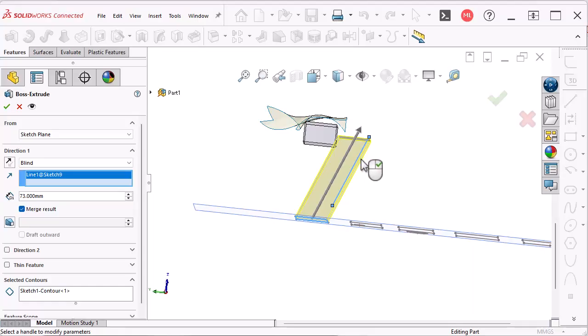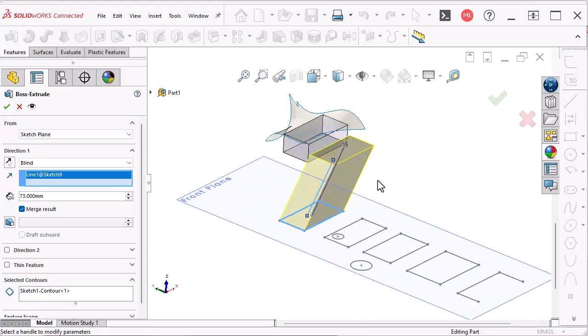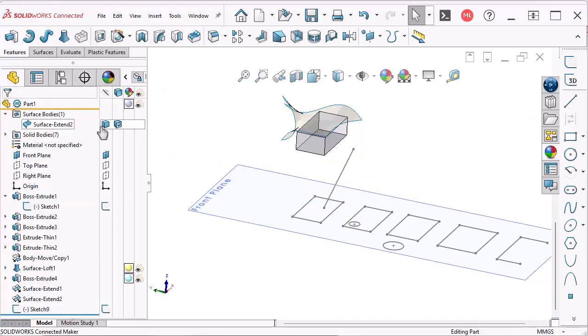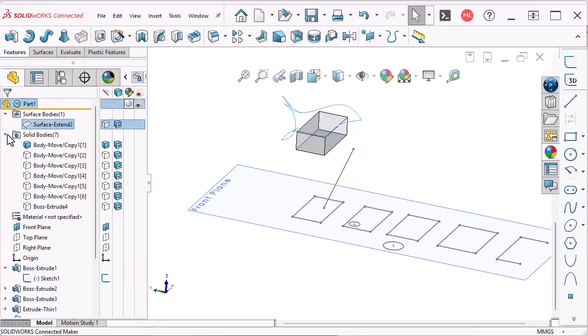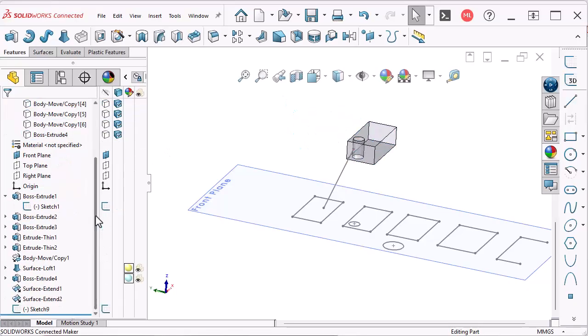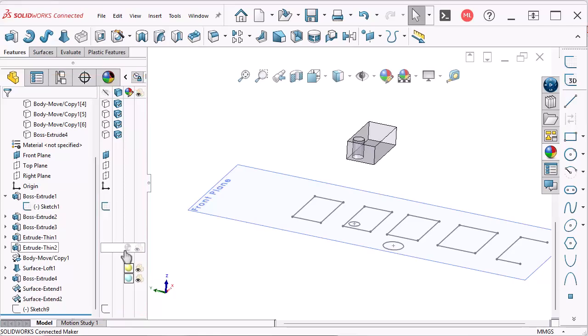And that angle can be given by an edge, a straight line. Could even be a sketch line in a 3D sketch. Doesn't have to be on a particular plane, but it has to be a straight line. An extrude that's not in a straight line is called a sweep, and we'll talk about that later. Those are these options. Let's get out of here, turn this off, and we'll go to the next option here that we're demonstrating. Also, we can turn off this sketch down at the end. If you haven't made use of the display pane, this is a fantastic tool for turning things on and off.